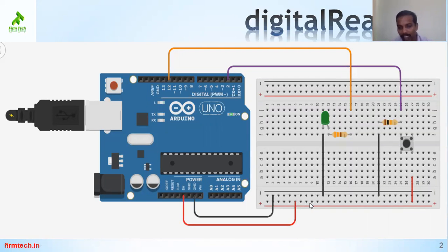If we connect the positive or 5 volt to this, it becomes the positive rail. So I haven't made any alterations, it matches the notations on the board, so this will be easy for us to identify. I have connected my 5 volt to this positive rail and the ground to this negative rail. And there is a little change in this connection. Yesterday we connected the negative directly to this cathode, but today we have connected it to the negative rail.